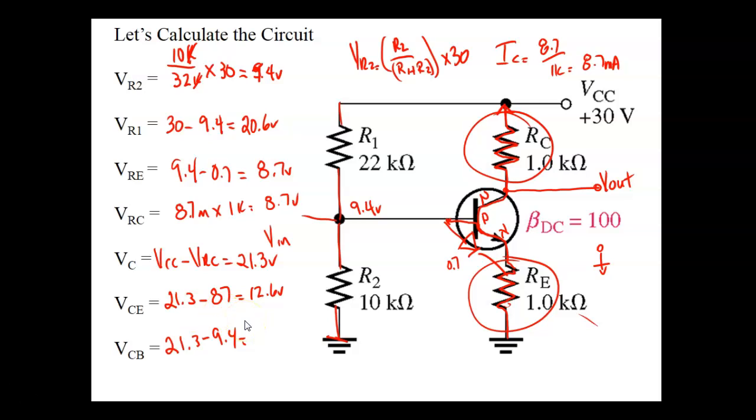Well, no, because we got 9 point. It looks like if I bring the 1 volt peak to peak in here, when it goes positive, it would go to 9.4, and if it went negative, it would subtract, right? So now that we got the base sitting at a voltage, it looks like I can add and subtract from that. But the problem is I can't.